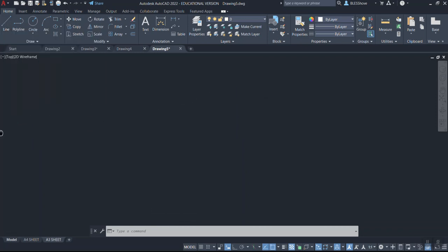And with measurement, what you need to do is click a line, specify first point. Now you drag to show the direction in which you want. Let's say, for example, I want to draw a receding line from this point that is 600 away from this point, but going in this receding form. I just show the direction. It means that if I put 600, it goes following that line. So the main idea now is to show the cursor the direction that you need. So as for now, I want it to be receding.